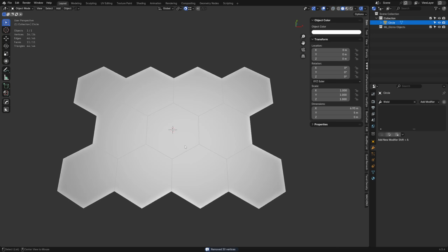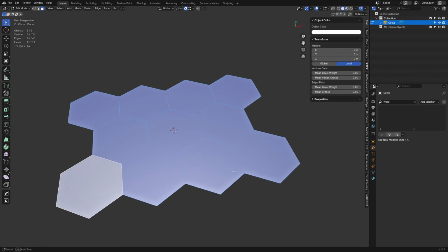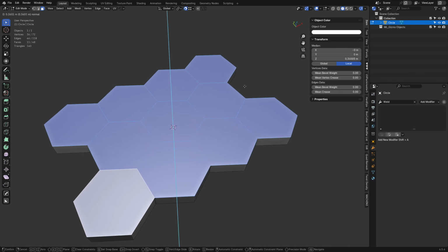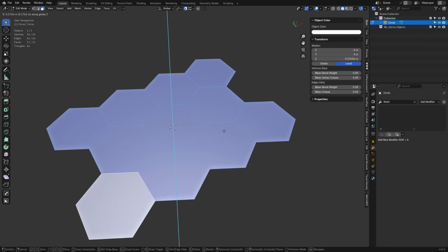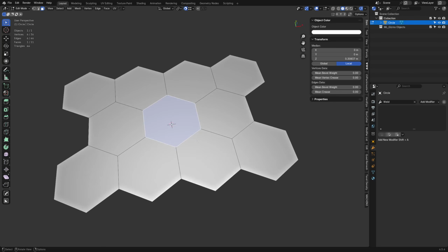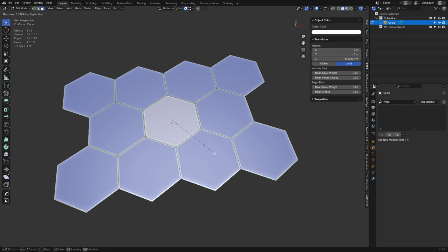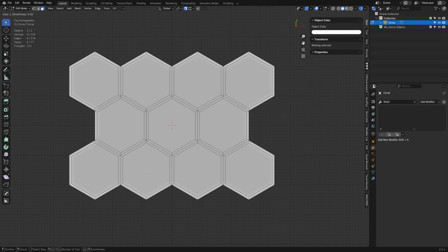Easier to model these when they're n-gons as well, generally speaking. So if we work with this like this, if I do an extrusion, this isn't actually, let's just move it up, G and Z. We'll come back to that. Let's say I inset all these. I press I to inset, and then I again to do individuals. Do this. Okay. Can't do loop cuts, so we have to use a knife tool and press K and hold shift, and I'll get center edge cuts.